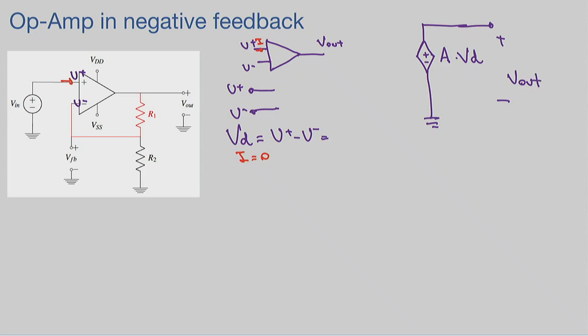That's what is inside this guy here, the op amp. Why can I neglect the other voltage controlled voltage source that I had there? Because we can pick VDD and VSS to cancel themselves, right? Then it becomes a simpler model.